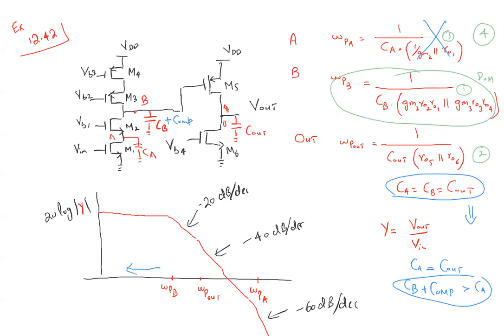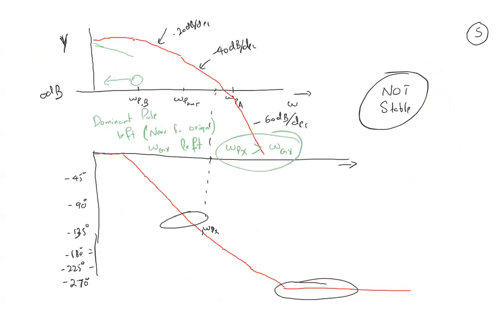The more it goes left, the better. But at the cost of what? Bandwidth will go down, because that is deciding my system bandwidth. The more it goes to the left side, it's okay, but my bandwidth will go down. So I can do this, but I have to be careful that if that bandwidth is acceptable to me, it's fine. So I can have a network like this.